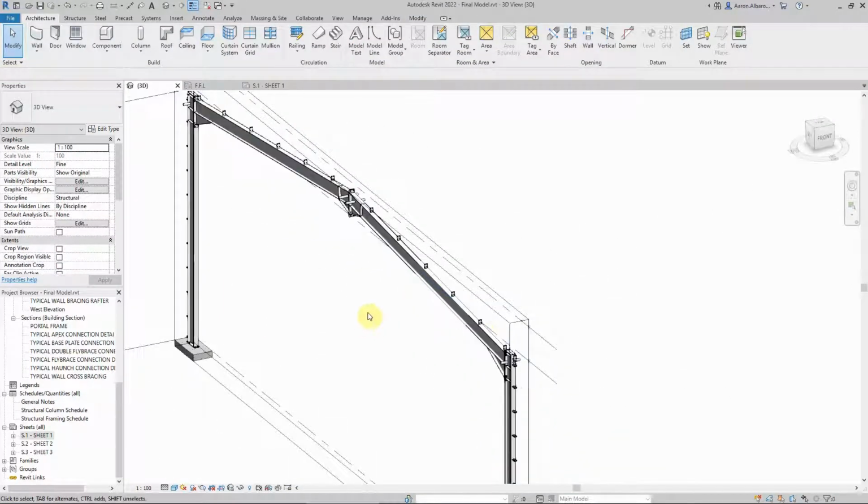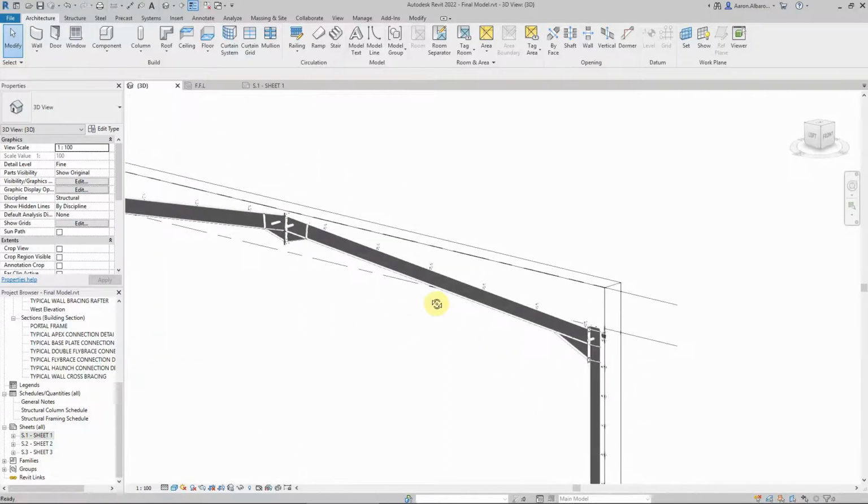Why? Because the main load we are expecting, or the main weight, let's put it this way, as a simple way of saying load, the main direction the load will be applied on this frame is downward in terms of weight, the roof weight, if there's any people working on site, if we have any solar panels, if there is any wind pressure, which is one of the major loads we have here, will be either pushing down or pushing up, applying negative pressure.